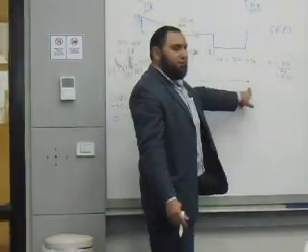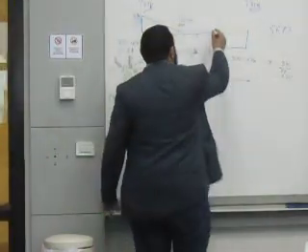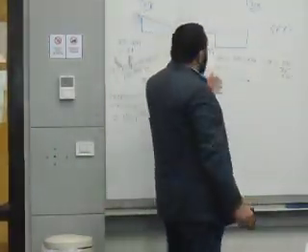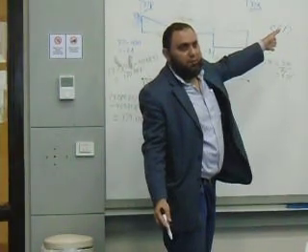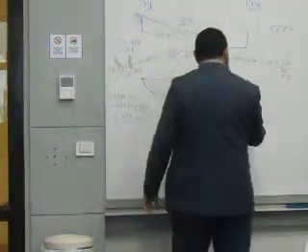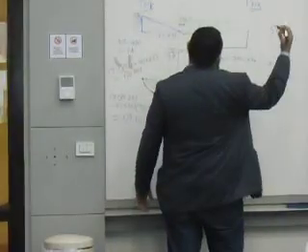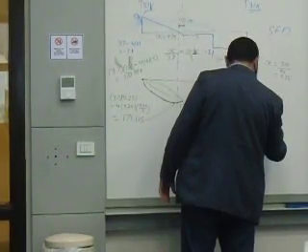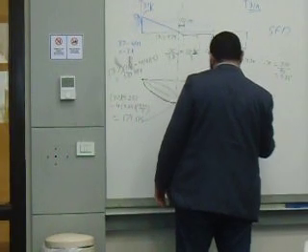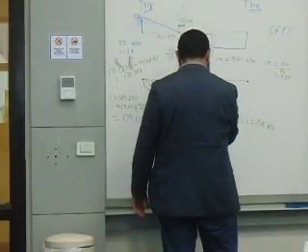We know this point is zero, of course. So we only need this point. By the way, here it's easier to look at the other side in my bending moment. So this point is simply 31, smiling, going up like a smile, 31 times 5, so this is 155. This point is 155.